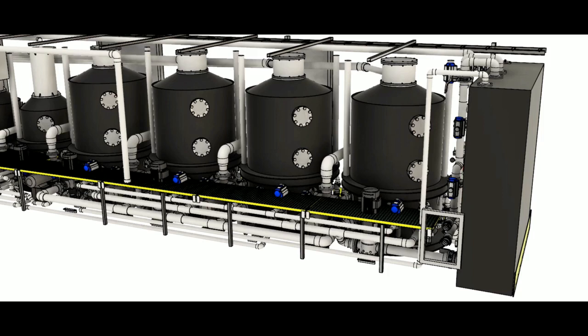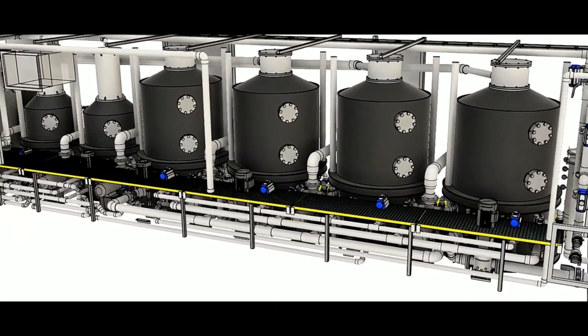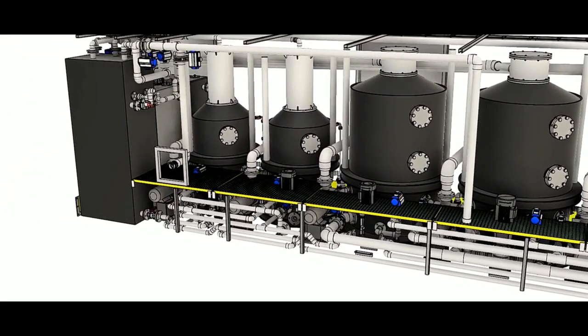The fractionate, or the harvested wet cut, runs out the top of the units, and then the treated water, which remains in the vessel, is then discharged and cleaned. So that primary fractionate collects in the tank on the left-hand side that you can see there, the dark grey one. And when it fills up to a level about 1,050 litres, we fill up one of our secondary fractionators. You can see the ones with the tall vacuum head there.